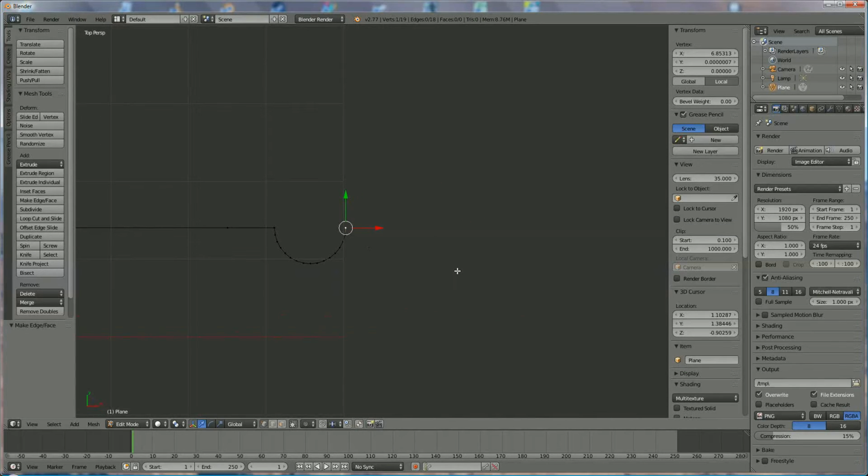Right click on that point and we're going to add a few extra points. To do that we're going to press Ctrl and left mouse click: one point, a second point, a third point. If you want to add a point over here you cannot do it because of the axis, so put away the axis, second point, third point and a last point. Okay, put on the axis. Now this is Y 0, this should also be Y 0, like that.